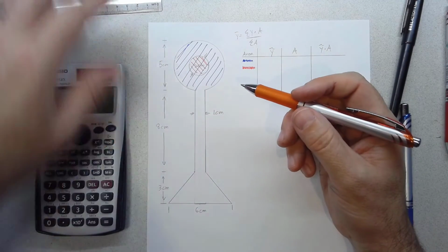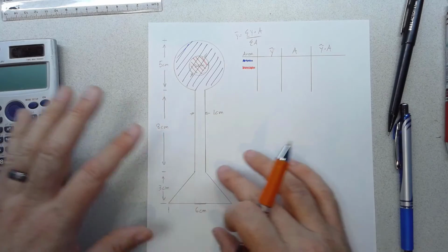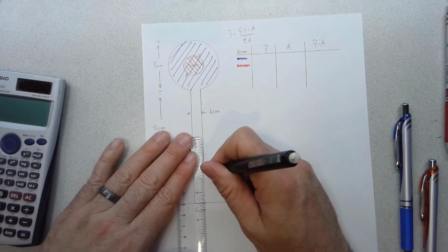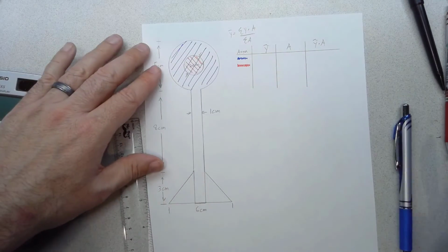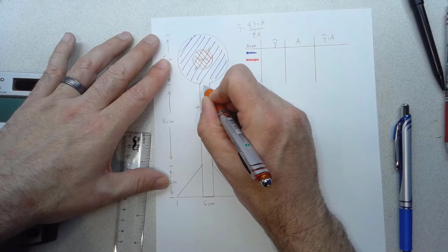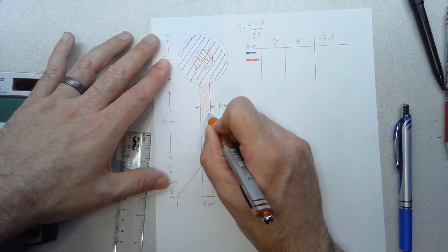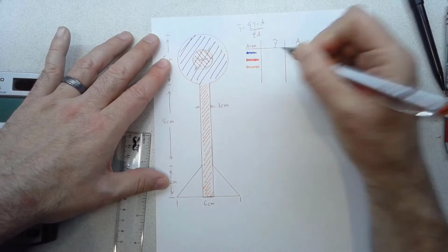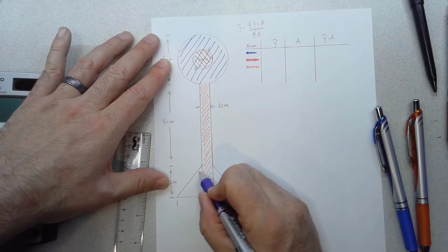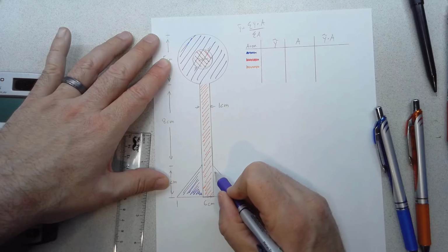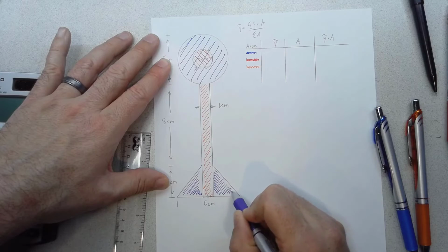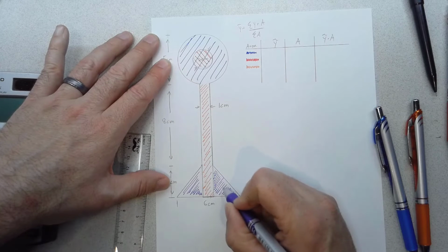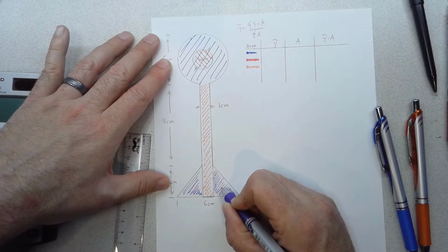And then let's look at this web. To make it easy, you could see I could find I of the trapezoid, but in my mind, it's easier to just kind of imagine this web continuing on running down through. And that breaks this shape into a rectangular section. So that's one area. That's the orange area. And then we'll look at these triangles as another area. And I'm going to shade them both as purple because they are symmetric about this axis. So if I find the value, the component for one of them, I can just multiply it times 2, and that'll be for the other as well.